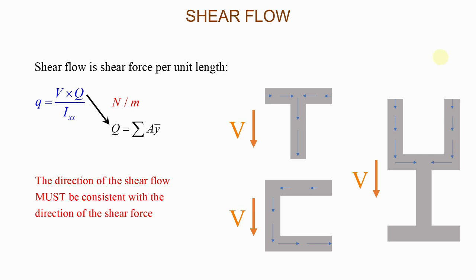And I told you to think of it as a flow of water. So if this stream comes here, and that stream also comes down this way, when they get here, they will meet. And here you will have the sum of both streams that will be going down, okay? And that is why my arrow sizes are different. It's because the magnitude of the shear flow increases as you move, okay? And so here it will be down like this. You will have the sum of these two streams here, and so the shear flow will be much bigger here, and it will go down like that.